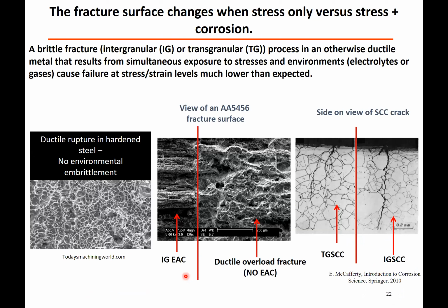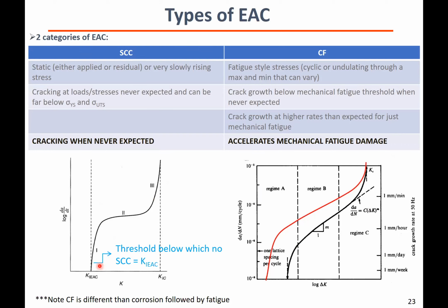Okay, so here are some micrographs where you can see intergranular growth, and that's in a real environment. And here you see the pristine material without any cracks, no embrittlement whatsoever. So what will happen? When we talked about crack propagation, we talked about it happening in 3 stages. You have the initial stage, then a steady state, and then the crack grows exponentially and really fast to K1C. And once it reaches your fracture toughness level, your material will fail.